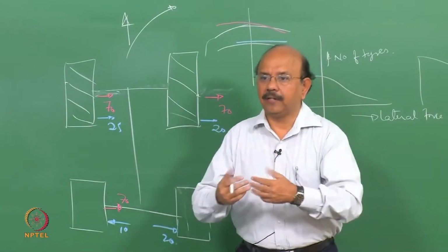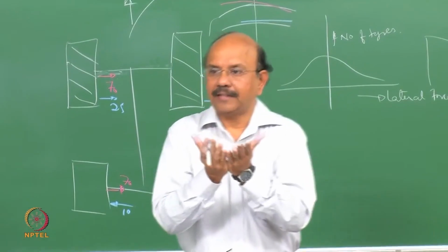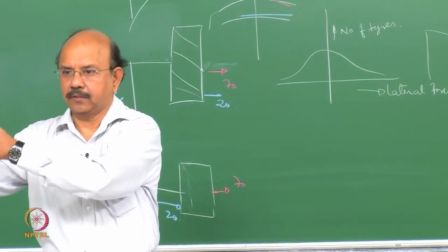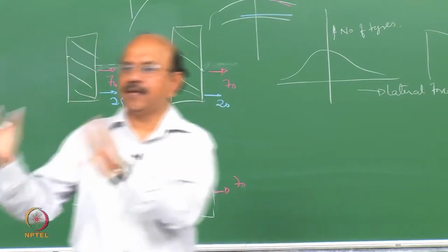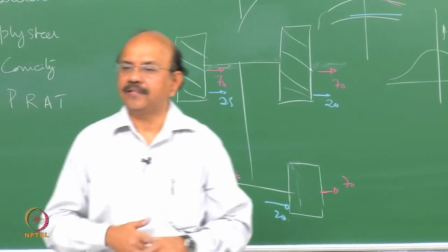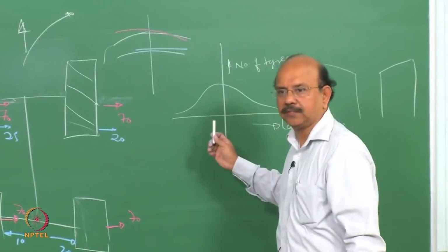As the tire is built, the belt is placed on a drum, and then it is taken over to a curing press and goes through what is called a curing process. So when this tire is manufactured, when they're placing the belt and then curing and so on, the belts do not stay in place. Remember that these materials are viscoelastic materials.